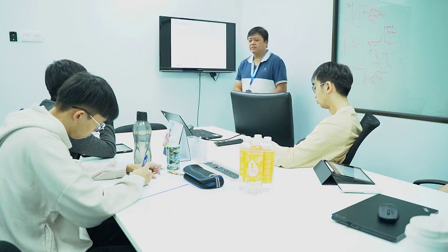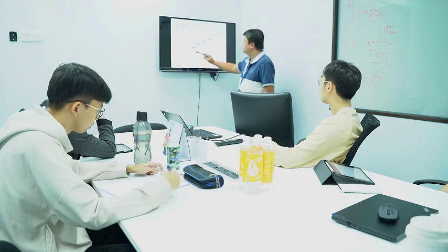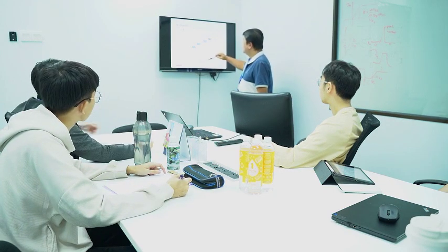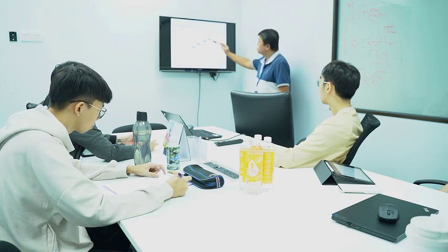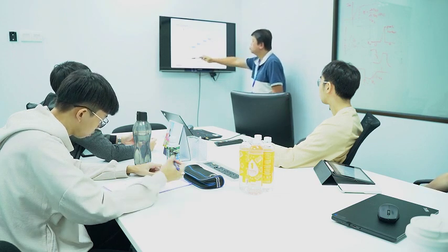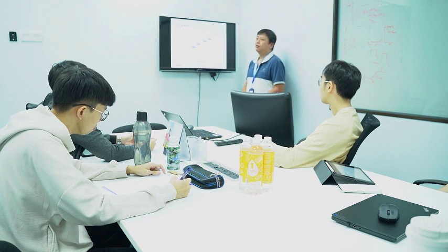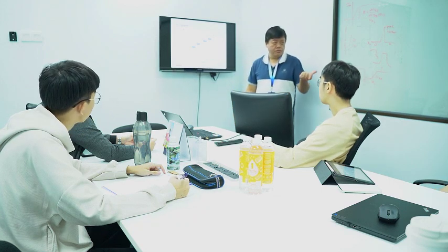So this curve also tells us that to reach 1 volt, you need at least, like this is 1 RC, 1 tau, 1 RC, 2 RC, 3 RC, 4 RC, and 5 RC. Only at about 5 RC can you get almost the full swing to 1 volt here, right? This tells us, okay, if you want a faster rise time, what should we control?